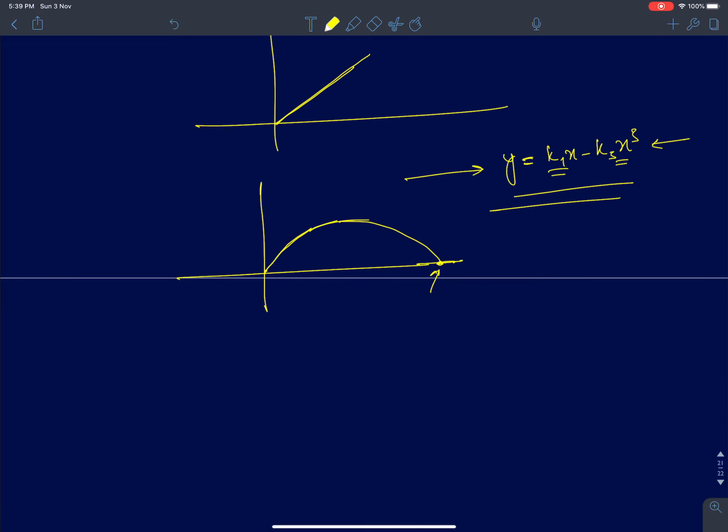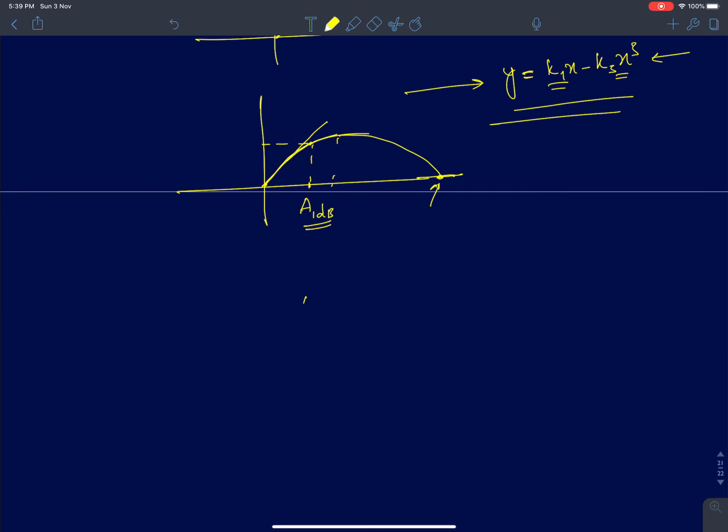Mainly we wanted to find out the point where the gain reduces by 10% approximately. In fact, it was 11% of its nominal value. And we call that point the 1 dB compression point. So that's the amplitude level at which the gain reduces by 11% of its nominal value. A normally here represents the peak value of the sinusoid. As we said, this is an RF circuit, so the inputs we apply are mostly sinusoids.